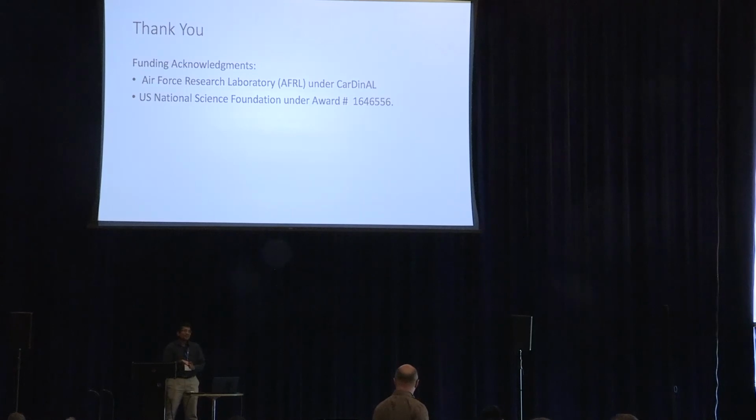Yeah, I agree with LQR. Maybe LQG. Yeah, so we need to try those things. But with trajectory tracking, you have to solve a time-varying problem. I don't know any tools for time-varying Riccati equations, so it gets a little difficult for us. But those comparisons, we owe those comparisons for sure. We haven't done them.